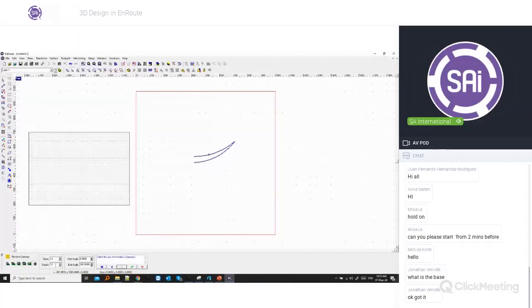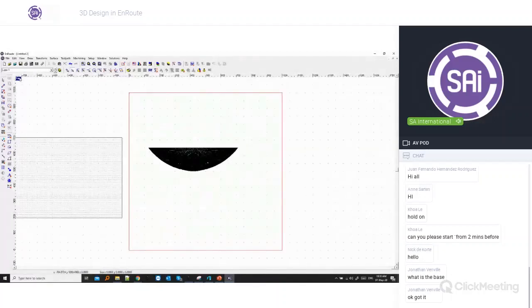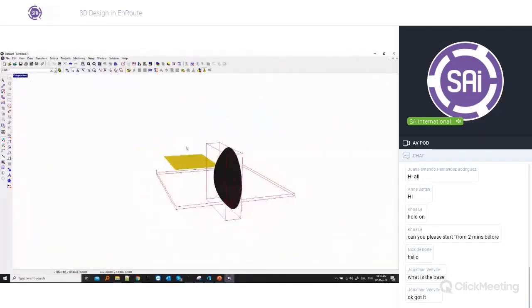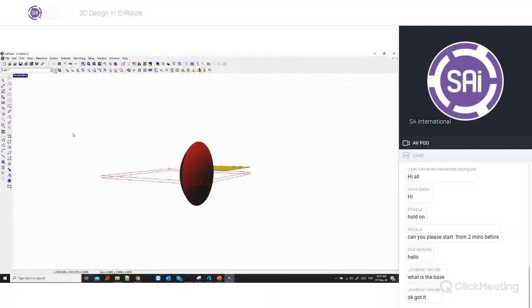So our slices here will be how many parts we make going across. So as I'm going to revolve it 360 degrees, I'm going to choose to make 360 slices. And our stacks will define the accuracy of our objects. I'm going to go for 50 there. And if I then hit OK and render this, you can see we've created a type of bowl.